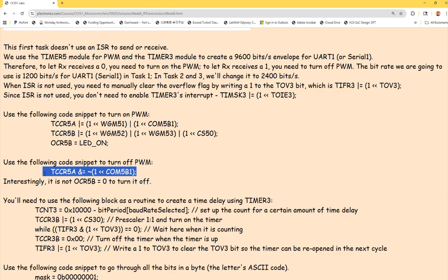Okay? So you can imagine the 1, remember for the UART protocol, 1 is what? 1 is the stop bit. Okay? So whenever all the data bits are transmitted, you just want to put it up to 1 to finish the transmission. So eventually you need to do that. That's at the end of the program, right? So you start sending the data, the start bit, which is this guy.